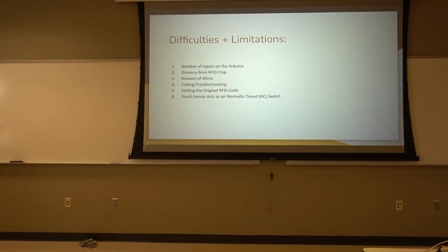Yeah, some of the limitations we had is definitely the size of our Arduino. We were going to go with some more sensor capabilities on it, but we've pretty much maxed out the entirety of what that small Uno R3 can handle. So the other thing is just the sheer amount of wires. There's jumper cables. It's just kind of unruly at times. It can get in the way, and sometimes even trigger the capacitive sensor occasionally.